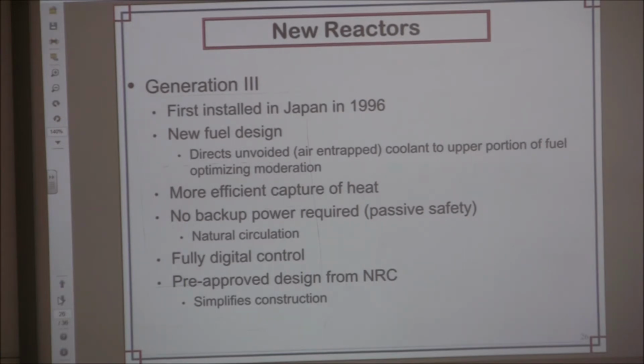It's more reliable inherently. It's fully digital controlled. It used to be everything was analog, so you had something turn on, and then this turned on something else and turned on that. This is all digital control. One of the projects I worked for when I lived in Washington, D.C. was getting a PLC, which was a triple redundant PLC that was used extensively for the fuel pumping refineries and stuff like that, where it was really critical not to have a failure. It was triple redundant, so you had one input, but then it would take that input and separate it and go to 3 completely different cards, and they would vote a 2 out of 3 condition, basically.